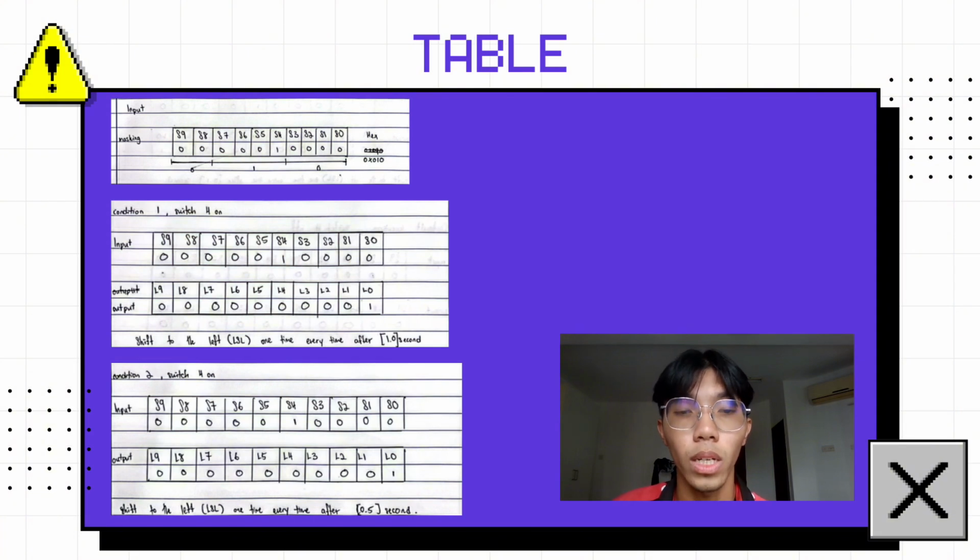When switch 4 is toggled on, its data register shows a 1 at position S4. The running light routine is called. It starts at the rightmost LED, L0, turning it on with a logic 1. The program executes a logical shift left one time every 1 second, causing that active high bit to slide smoothly from right to left across the LED bar.